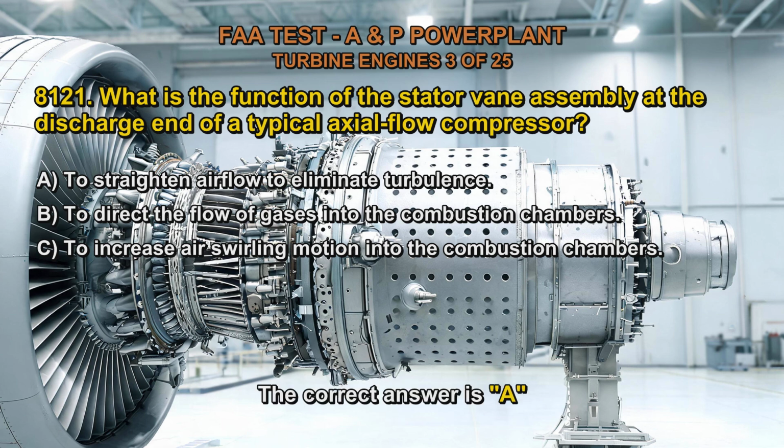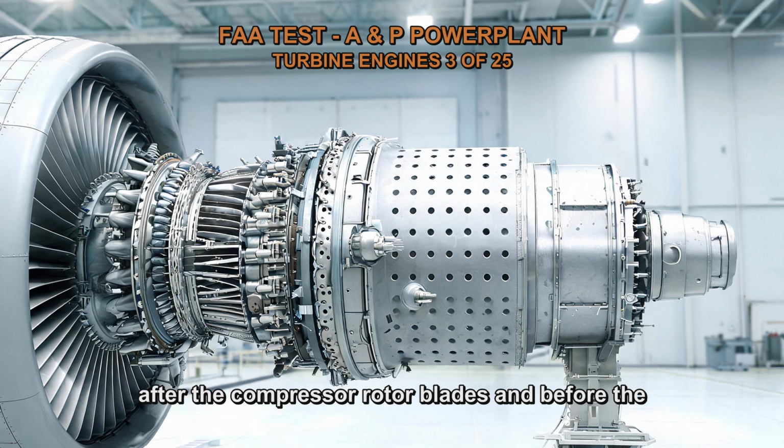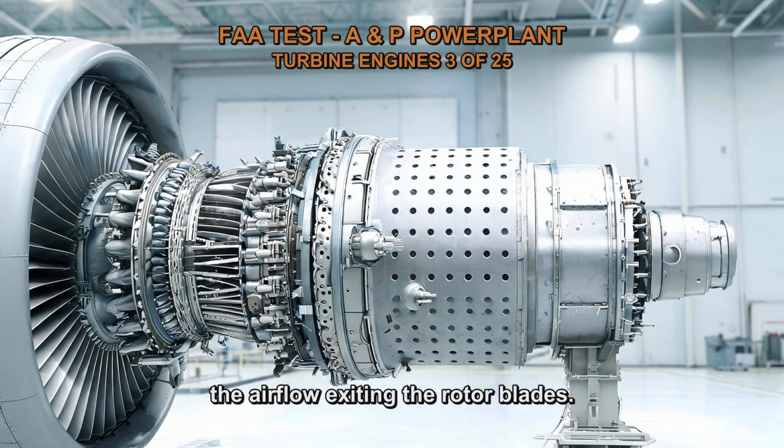The correct answer is A. The stator vane assembly, also known as the stator guide vanes or stator blades, is located after the compressor rotor blades and before the combustion chambers in an axial flow compressor. Its primary purpose is to straighten and guide the airflow exiting the rotor blades.